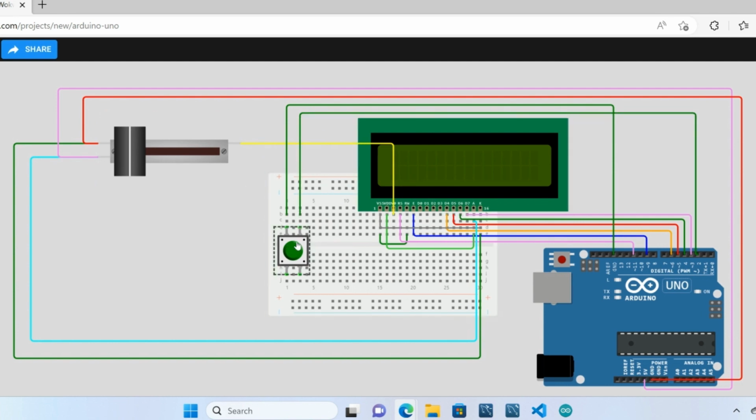So here, remember, we have the push button that we press to make the sprite or the character jump. We have these two at the end. We want to make sure that the second one goes to pin number 2, and the first one goes to ground. Here's a potentiometer. Oh yeah, and on the breadboard, everything is connected, so it looks a little bit different here, but of these two wires, this one is connected to 5 volt, and this one is connected to the ground. I'll show you on the actual breadboard, but this is kind of just a breakdown of it.